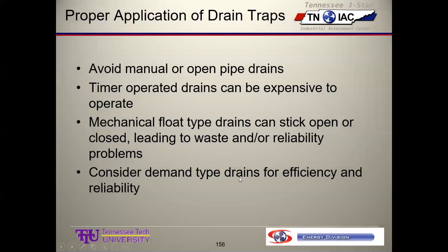Timer operated drain traps. We'll see some of those. They have 2 switches on them. One says, how often do I open? And the other says, when I open, how long do I stay open? And they're just 2 different dials, and you set them. And it's a leak on purpose.